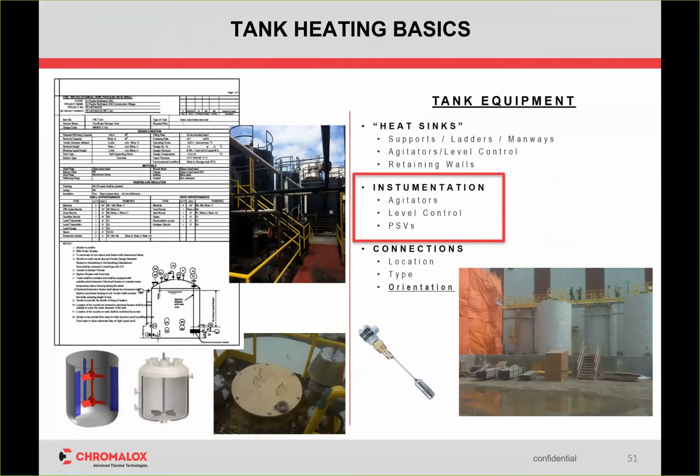A little bit back to design, when you are talking to a customer and you're back to that data sheet, something that doesn't always get illustrated on there, you might have a lot of connections and ports that are noted on there, but they don't really say what they connect to or what's in the tank. A lot of times tanks have agitation, level control, pressure relief valves. You need to take those into account. And simply bringing them up and having the discussion with the customer will let them know you know what you're talking about. You want to walk through that with them.